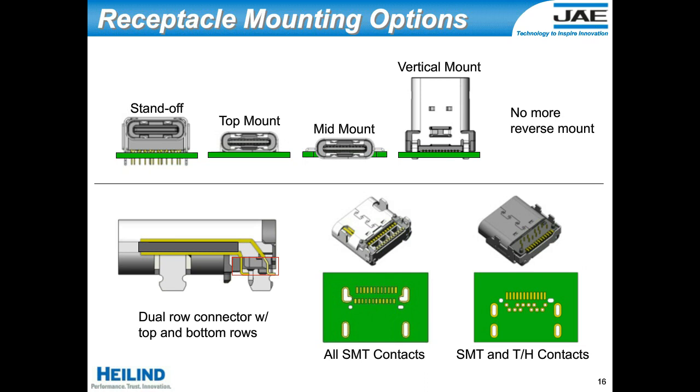However, typically for high signal integrity requirements, surface mount contacts perform a little bit better than through-hole contacts. However, again, through-hole contacts do give a little bit of possibility for reworking. In terms of board retention, hold down and things like that, between the hybrid type and a dual surface mount type, there really isn't too much of a difference. It's more or less the placement of the large shell hold down pins that makes a difference for the actual shell retention.